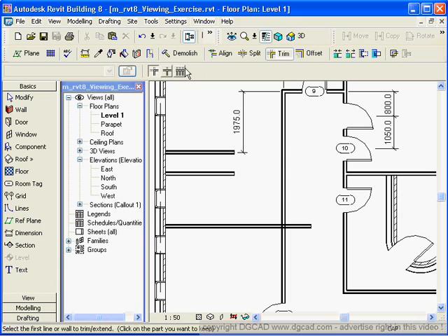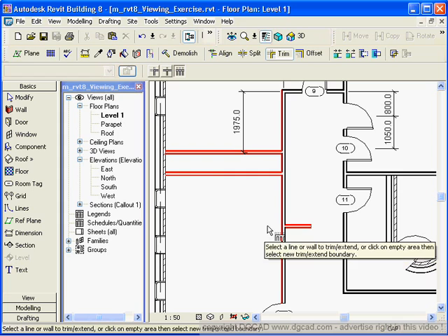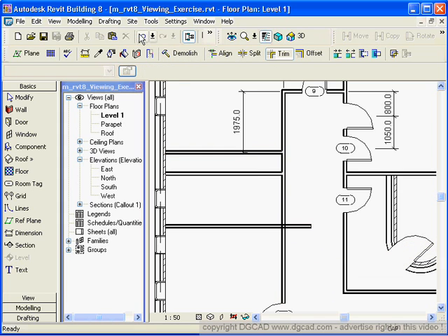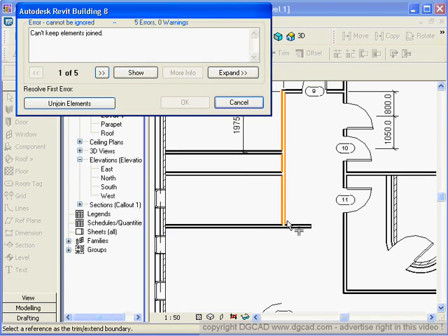Okay, so I can go to this trim here, and I can use this type of trim. I'm going to pick this as my object and surface, and that's going to go to there, that's going to go to there, and then this one's actually going to do that on that side. If I would have picked the other side, it would have gone the other way. So that is kind of like trim and extend all in one. And then there's this type of trim. We can go in here and pick on there, and it will trim the first one about the second one.